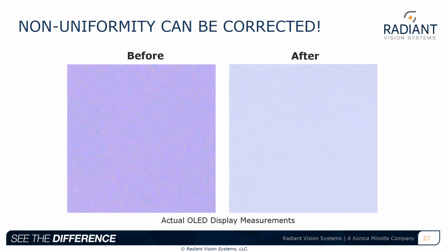The representation and use of a synthetic measurement, and measurements over many gray levels, allow additional correction. What we will propose soon is the Demura solution to create correction coefficients. The left image represents an actual OLED display prior to correction. One can note that there is some sort of color variation on the image, and after the correction process and measurement, we greatly reduce any color variation of the display.